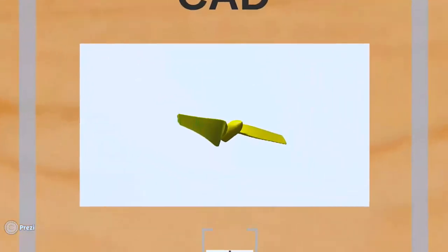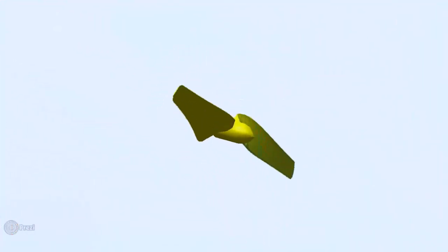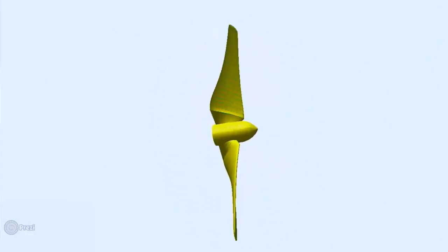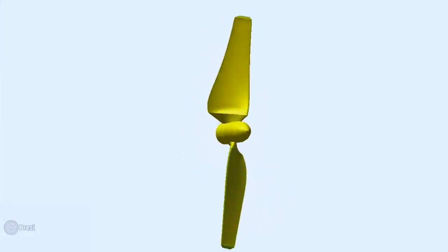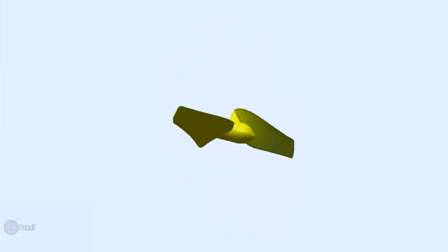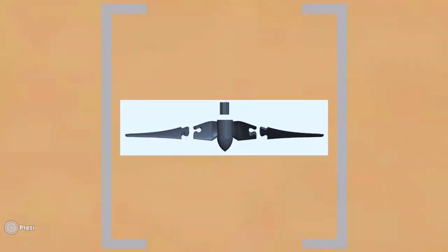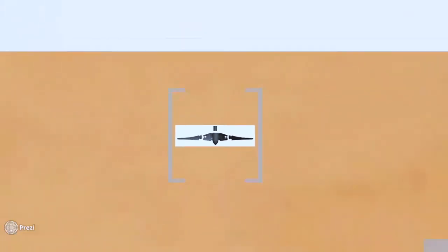Here is a virtual model of the design made in Creo Parametric. This is done by using the twist and chord length distribution to discretize the blade into 21 planforms and blend them together. Since the rapid prototyping machine can only print objects up to 200 mm, our design must be separated into 3 sections. The cut at the blade is made to be a dovetail shape so that the parts can lock up on each other. It is also rounded so that there wouldn't be stress concentration on angle junctions.